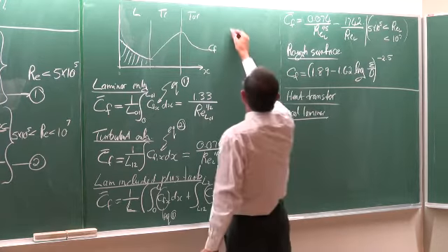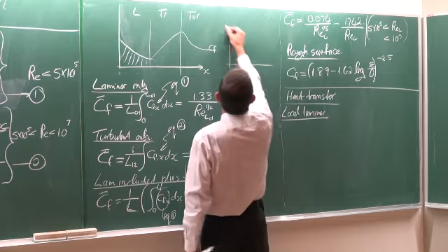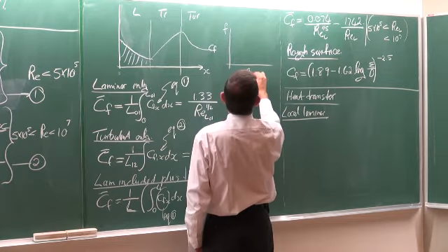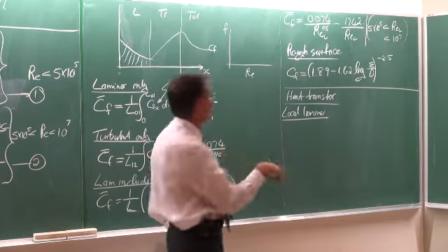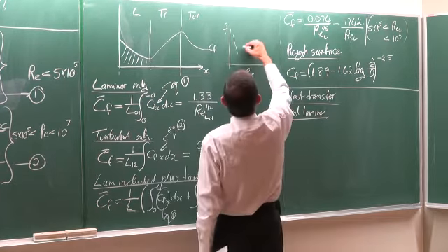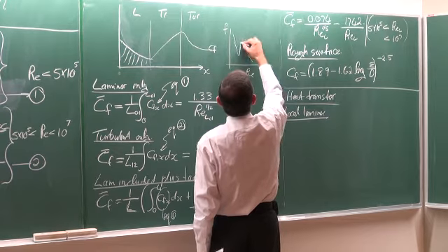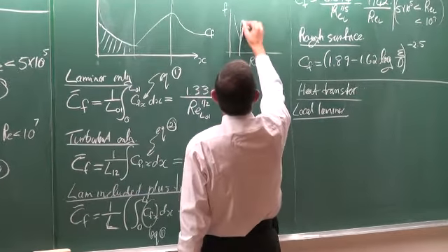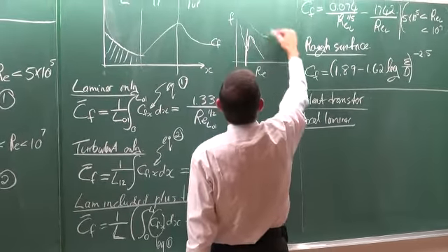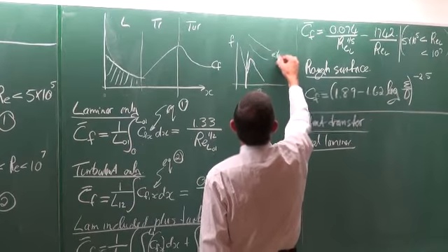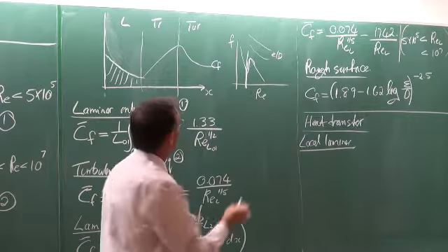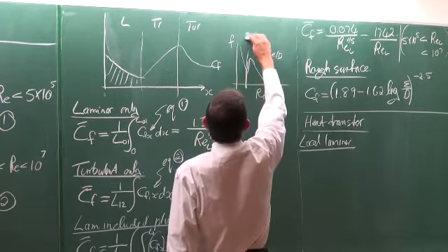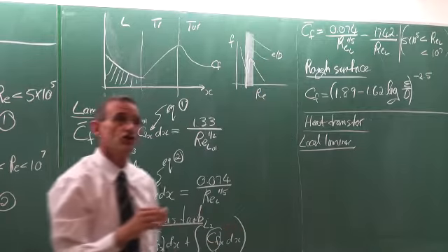So typically, if you look at the friction factor in a tube as a function of Reynolds number, you get something like that, and that is the transition point, and then you have all the other lines there of roughness, and in the Moody chart you will see that area there is gray.